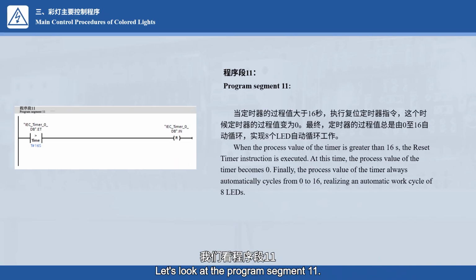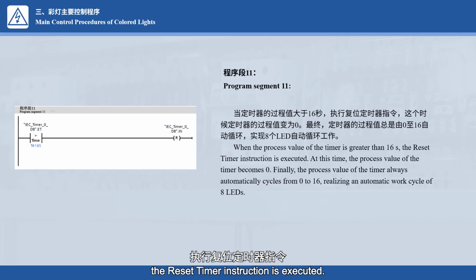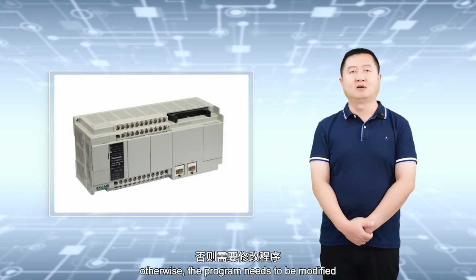Let's look at the program segment 11. When the process value of the timer is greater than 16 seconds, the reset timer instruction is executed. At this time, the process value of the timer becomes 0. Finally, the process value of the timer always automatically cycles from 0 to 16, realizing an automatic work cycle of 8 LEDs. After the program is written, we can verify in PLC whether LED lights can be controlled as required. If so, it indicates that the programming is correct. Otherwise, the program needs to be modified until the requirements are met.